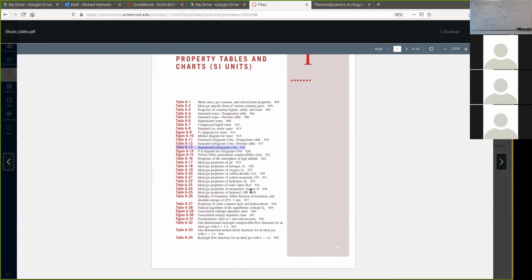You have pressure and you're looking for a saturated mixture or saturated liquid. Is it 12? A12, exactly. A12 is the pressure-based table for saturated mixture. So when you go to table A12, what variables are you going to take? Because quality is 0, what variables? Subscript f or subscript g? Liquid or gas? Liquid, which is f. Perfect. So liquid is subscript f.